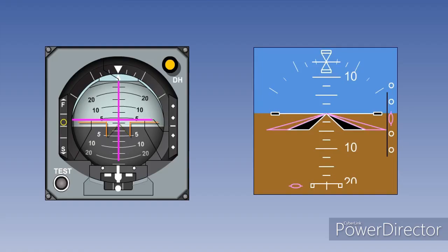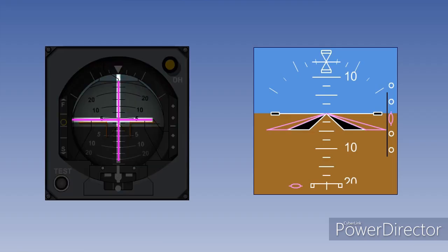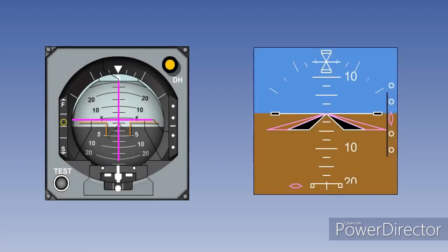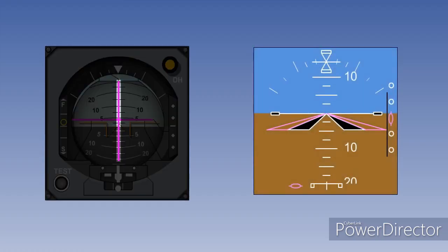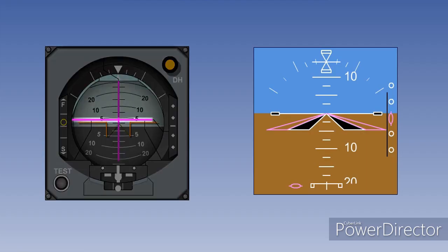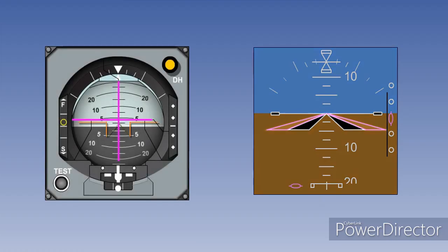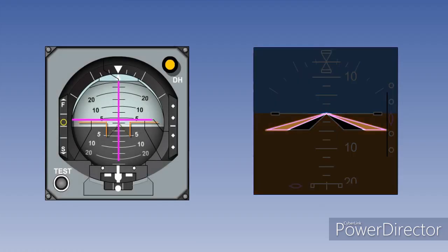The flight director system uses one of two ways to display the information, either using twin bars forming crosshairs or a V-bar. Both demand pitch and/or roll inputs from either the pilot or the autopilot. With the twin bars, the vertical pointer displays roll commands, and the horizontal one displays pitch commands. The V pointer moves as a whole unit to command roll and/or pitch inputs.